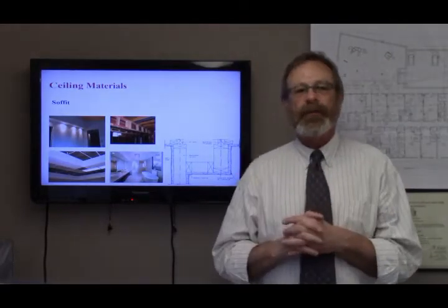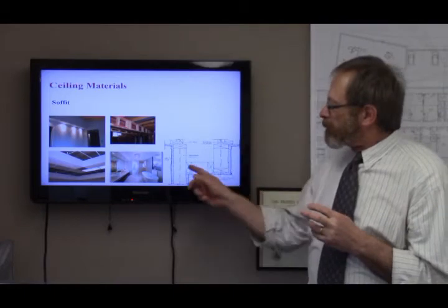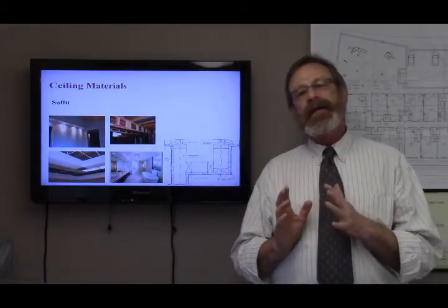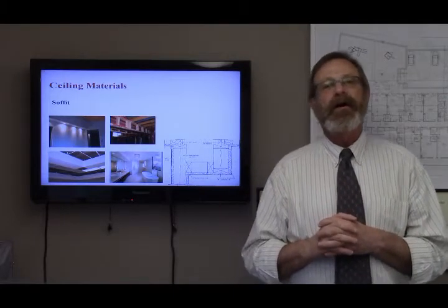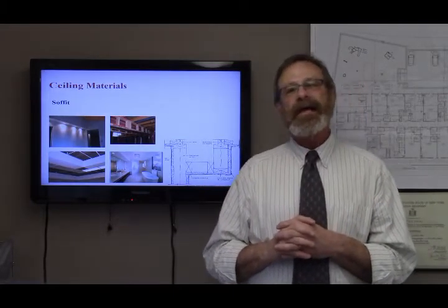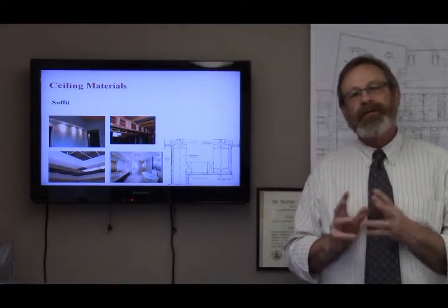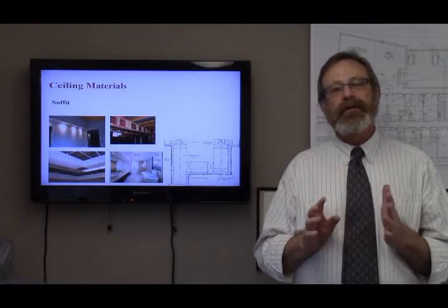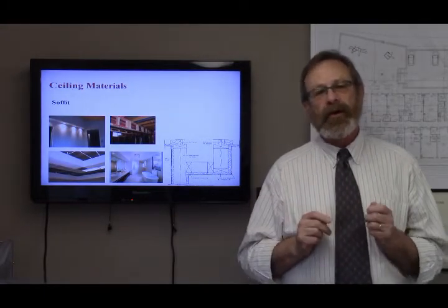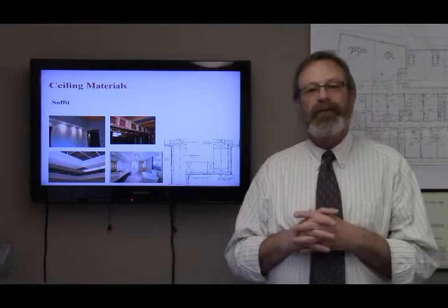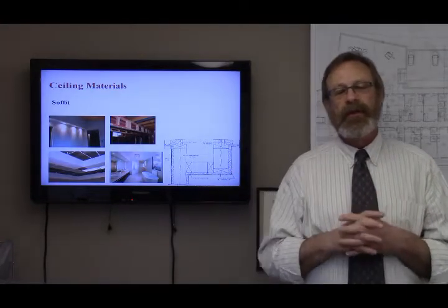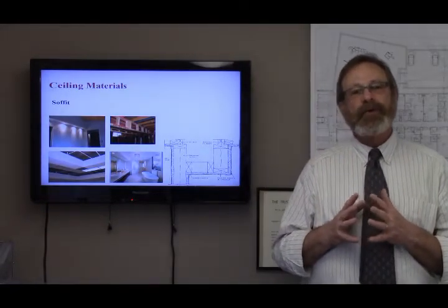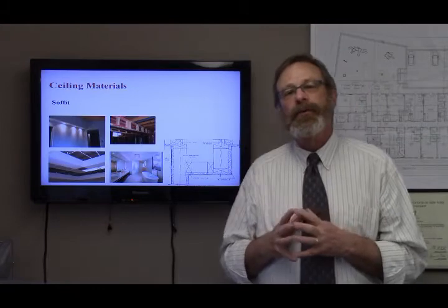I mentioned the soffit before. Here's how a soffit is drawn. This is a detail. The soffit is an informal term for any kind of boxed-in area that hides structural elements of construction, such as beams, arches, or stairs, or services. Services include heating, ventilation, and air conditioning, which we refer to as HVAC, ductwork, electrical wires, and plumbing pipes. A soffit has no structural purpose unto itself.